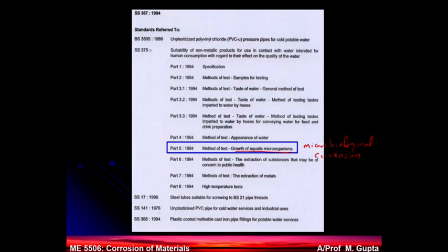So whether you are using the pipe for transporting water, or you are using the pipes to transport oil, or you are using the pipes to transport chemicals, for any purpose, corrosion is always a big issue. When you have pipes with hot liquids, with insulation, then corrosion under insulation is always a big issue. So you have to have a good understanding of corrosion and how to manage it. The idea is management. If you understand all these things, you can take the best possible step to minimize it. You cannot eliminate it, but you can minimize it.